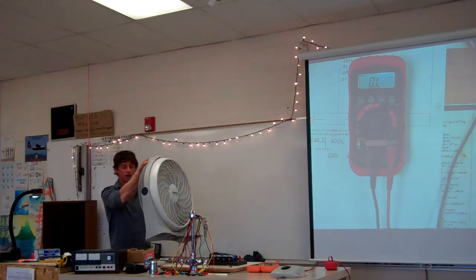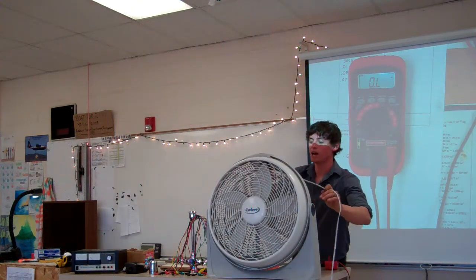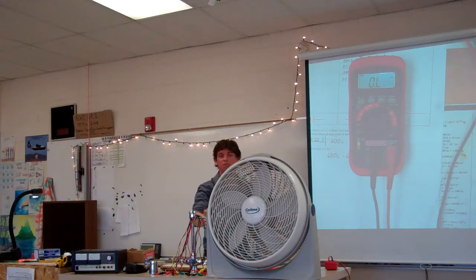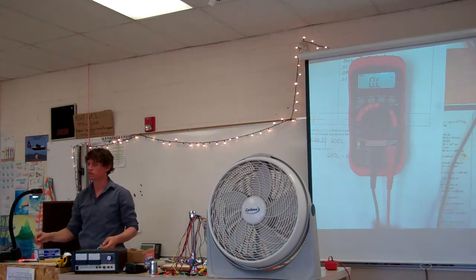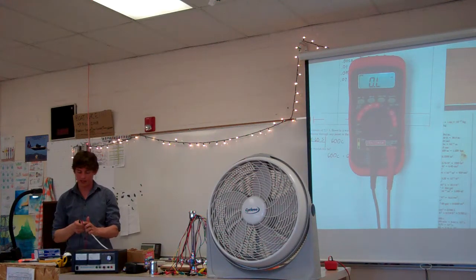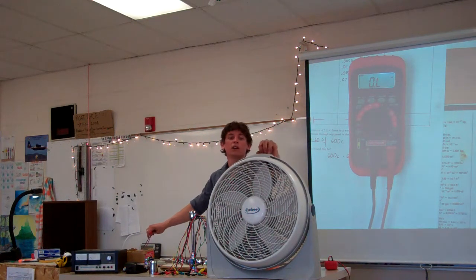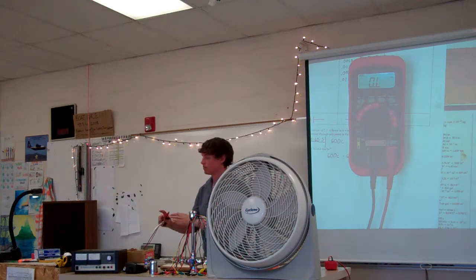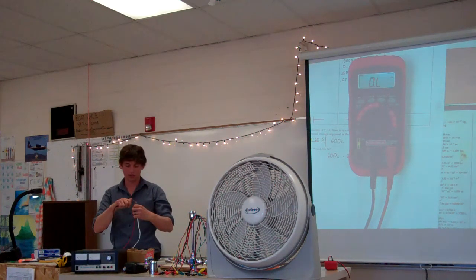So let's take this fan. It's a big fan. You're noticing maybe that I'm not measuring the resistance when things are plugged in. Resistance is always measured when there's no current flowing. I'm not going to take this ohm meter and start connecting it when things are actually plugged in. Okay, so it's got a switch at the top. And to measure the resistance of something that plugs in, you simply do this.